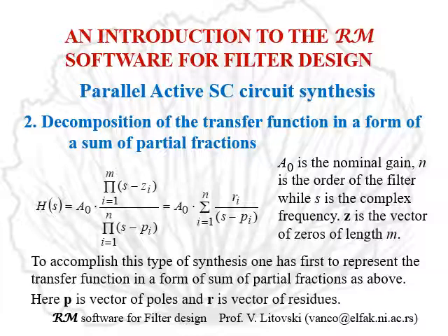On the right-hand side, we have the same transfer function expressed as a sum of a ratio of a constant, which is called a residue, and a difference between the frequency and the value of the pole. This form, in fact, since it is summation, allows for parallel realization.